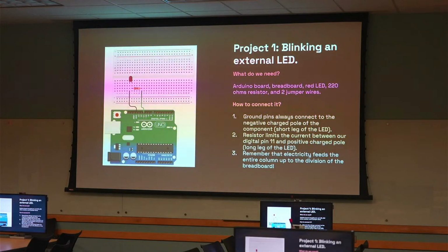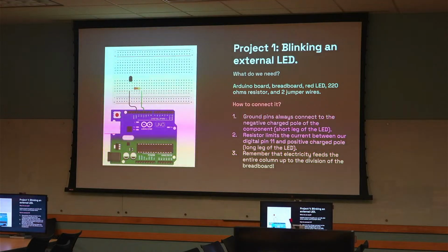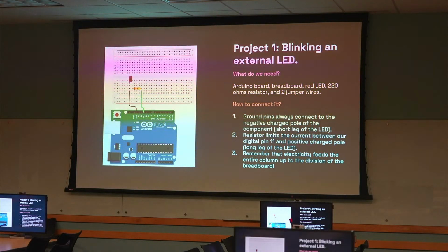And then you get a shorter wire. You connect the 11. This pin 11 is right here. Yeah, exactly, 11. And then you connect it to that pole of the resistor. The positive pole? You should do it here, in the same column. It could be anywhere within the same column. Is that in the same column?